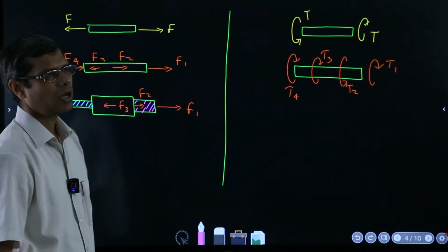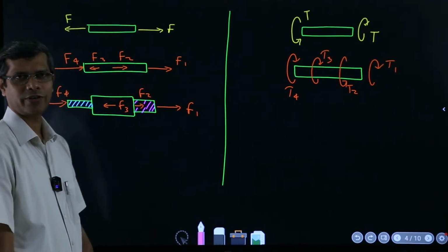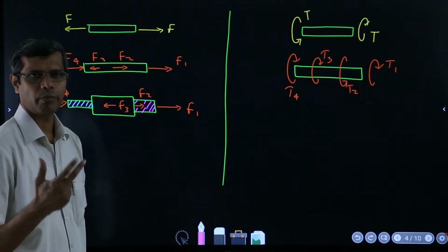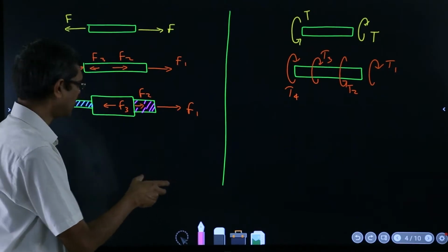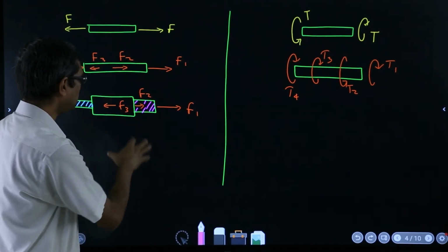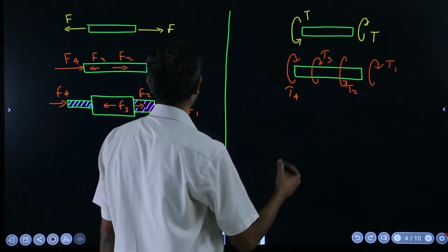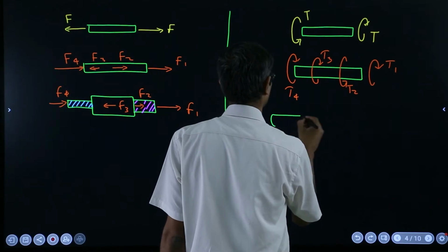That means now I am talking about the splitting into different free body diagrams, if you remember. Wherever you have a force, material or area discontinuity, you have to split them. That concept will be used in such a case, and exactly the same conditions can happen here. You can have a case like this.